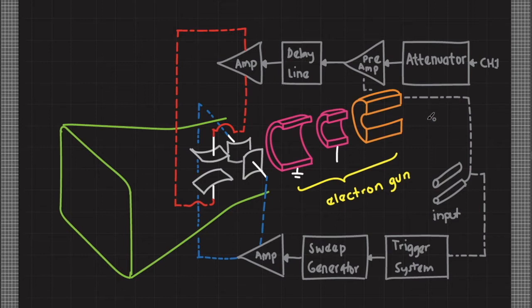So just to give you an overview, if this is the part where we feed the signal, it is connected to a circuit that regulates the amount of horizontal and vertical deflection of the electron beam, and thus its overall effect is to display whether you have a time varying voltage or simply a DC input voltage.